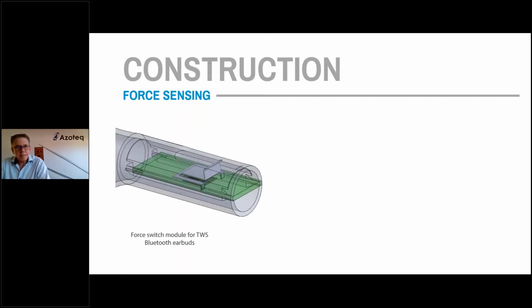Now the inductive sensing is very suitable for force sensing as well. Whereas before we measured the instantaneous click of the metal dome, for force sensing, we measure minute deflections of the metal target. The example that I have on the screen is the stem of a Bluetooth earbud. Maybe many of you would be familiar with something like the Huawei earbuds or the Apple AirPods, which have the small microphone boom. This is a very suitable user interface to squeeze between your thumb and your forefinger.